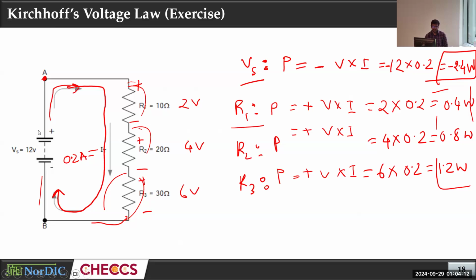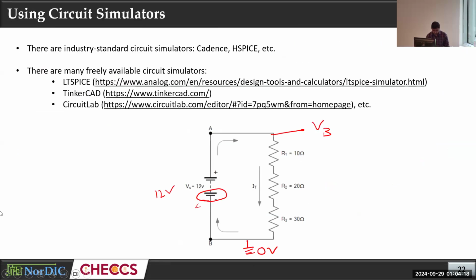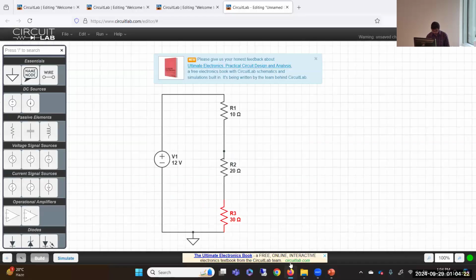So when you see the current of this voltage source, there should be negative current. That's why it's showing negative current. Positive volt is 12 volt and power is negative. You see the 2.4 watt supply power. Is it clear? So that saves a lot of time, right?